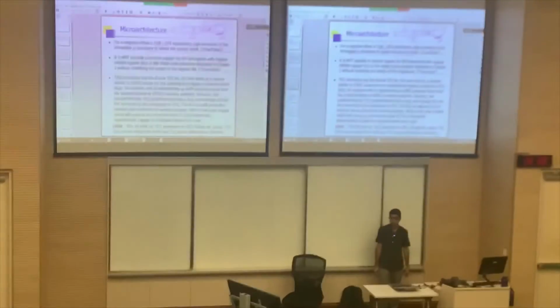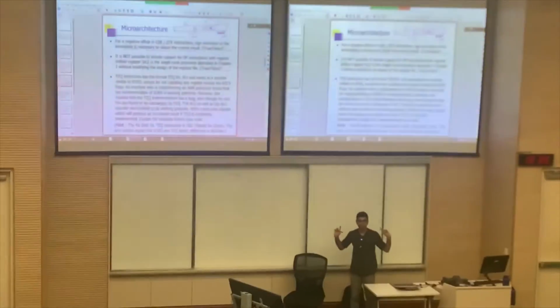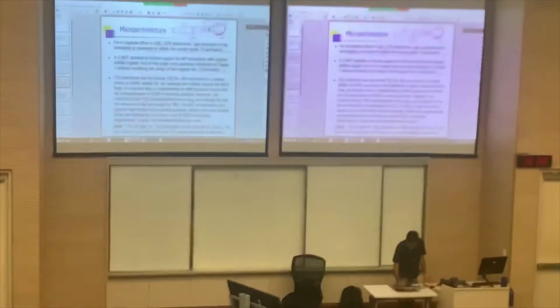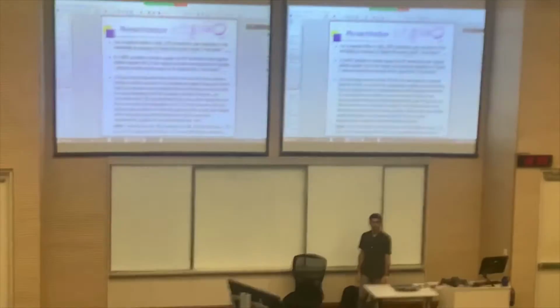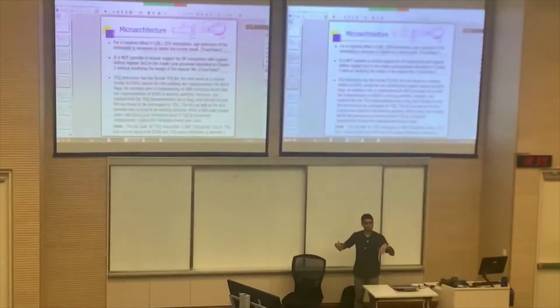So do you need sign extension of the immediate? The answer is no. You can think of it as a sign and magnitude system where the magnitude is encoded as the immediate and sign is encoded as the U bit. You will never do a sign extension to something which is a magnitude. Magnitude means it's always positive, right? So you wouldn't do sign extension.